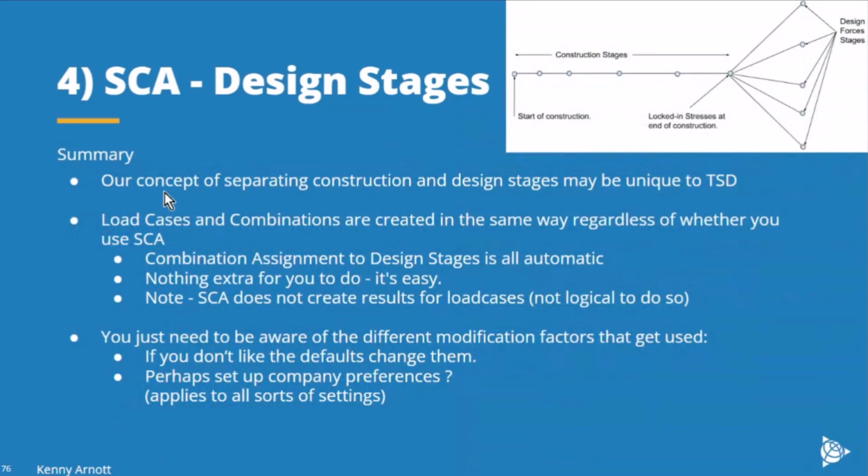So, in an overall summary, a reminder that our concept of these construction stages running along a linear timeline and then forking into a series of 5 design stages may be specific to our implementation of stage construction analysis. In all of this, the load cases and combinations that you create are unaffected. You create them in exactly the same way, regardless of whether you intend to do stage construction analysis. The combination assignment to design stages is all totally automatic, so there's nothing extra for you to do.